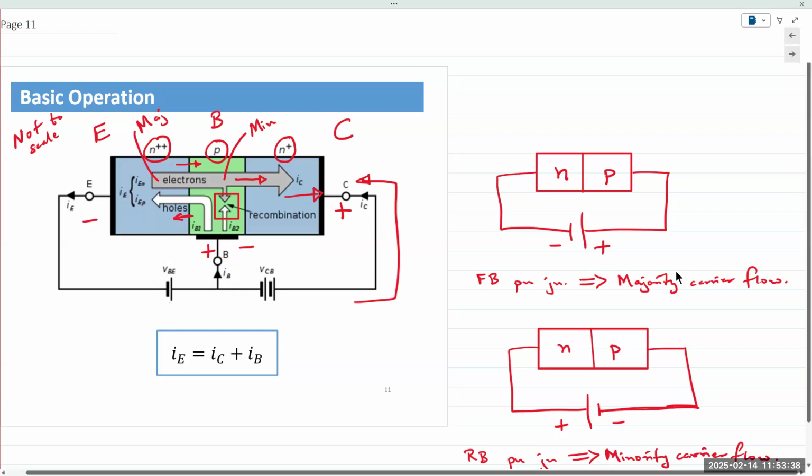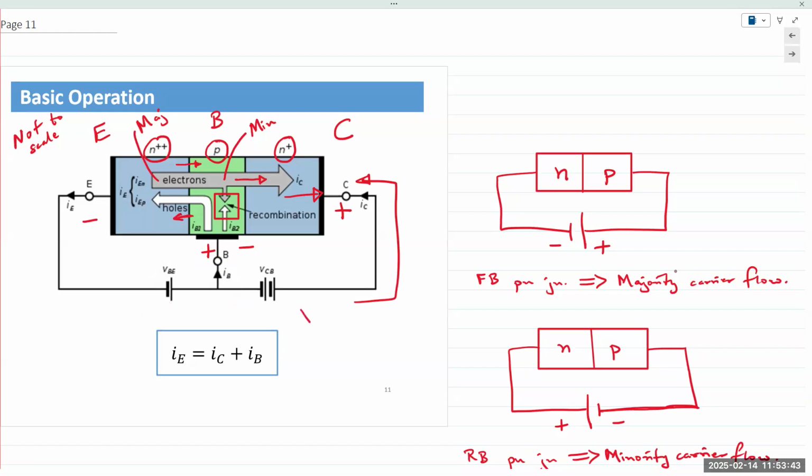So typically what we'll do is between the collector and emitter, we would have a biasing voltage called VCC. And this VCC, just for practical purposes, let's say would be 10 volts to, let's say, 15 volts for experiments in the lab. The base voltage would be far smaller.